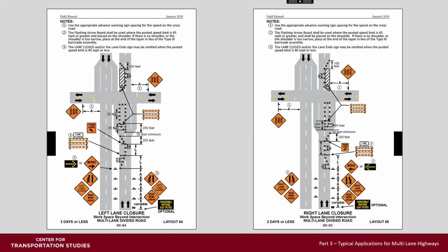These layouts are similar to the layout we discussed earlier on selecting distances and determining proper device location. Please note that the lane closure tapers in advance of the intersection direct all the traffic into a single lane. Again, this is done to give drivers one decision at a time, providing for predictable driver behavior as they approach the work area.